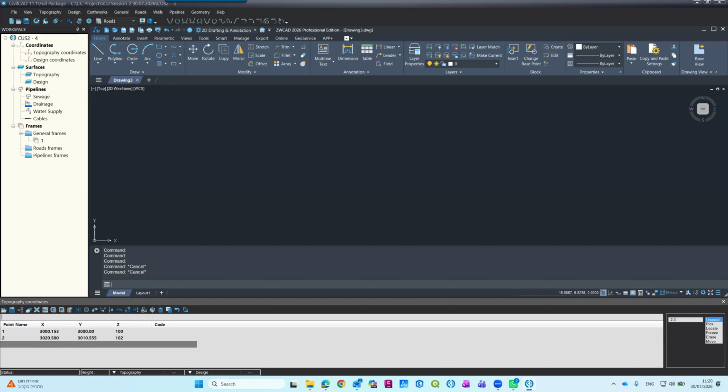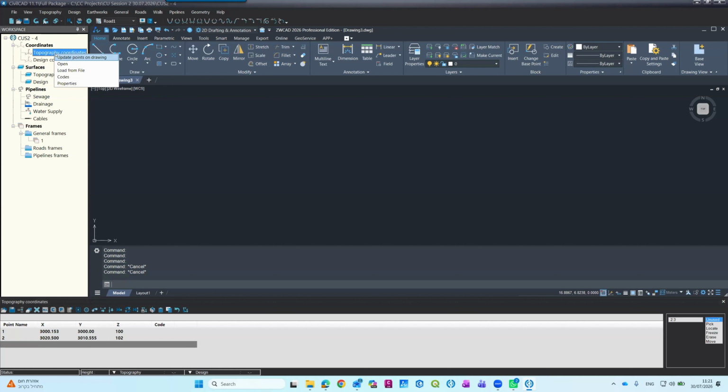And if I want to see the points, there are two options. One is to press the refresh button, which sits here on the top. The good thing about the refresh is that it will refresh all the coordinates lists that you have. The bad thing is if you have many coordinates lists and you don't want the software to scan the entire list and update them, this will take much longer. So the fastest way is to stand on the list here, right click, update. And that's it.